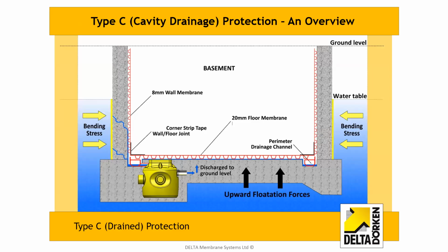And that's a nice slide, just showing what a cavity drainage system is. Very simple, doesn't rely on perfect workmanship, can be tested during construction because we can flood test the channels and make sure it's going to drain effectively. It's the only system that really can be tested properly during construction, and it's a nice, safe, passive system to cope with seepage.